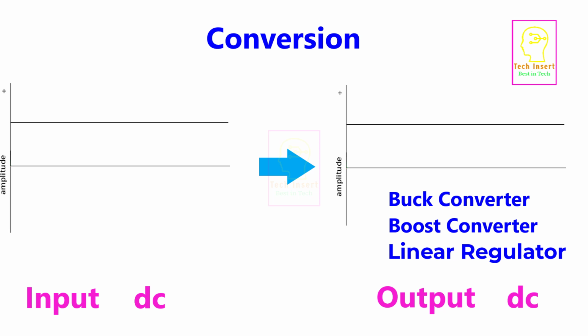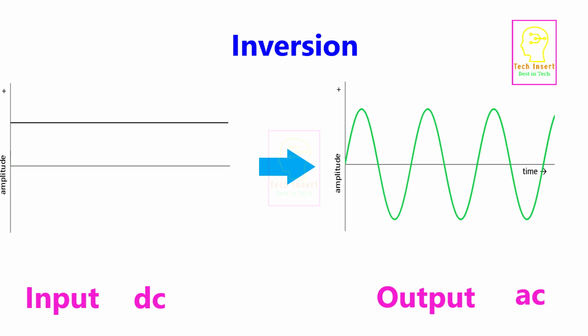In a buck converter, they will use switching operation to regulate the output voltage. In linear regulators, it will dissipate the additional energy as heat and will regulate the output voltage. That is why efficiency is good in buck converters. TPS5430 is an example chip for buck converter. Similarly, 78XX series or 7805, 7812 are examples of linear voltage regulators. Buck converters are costly.